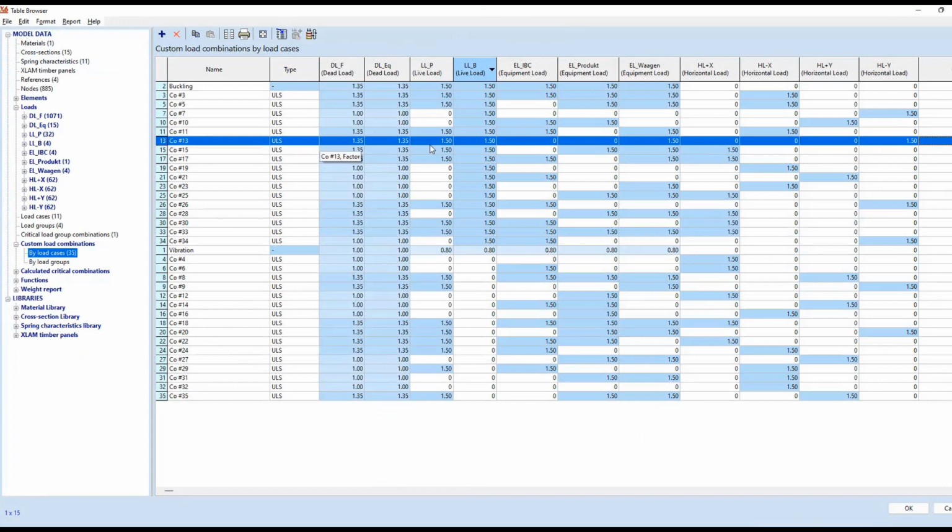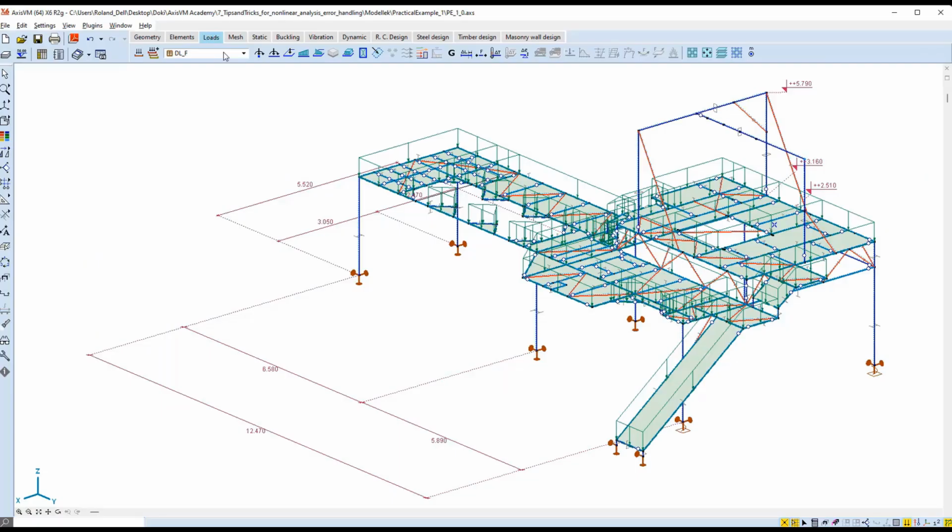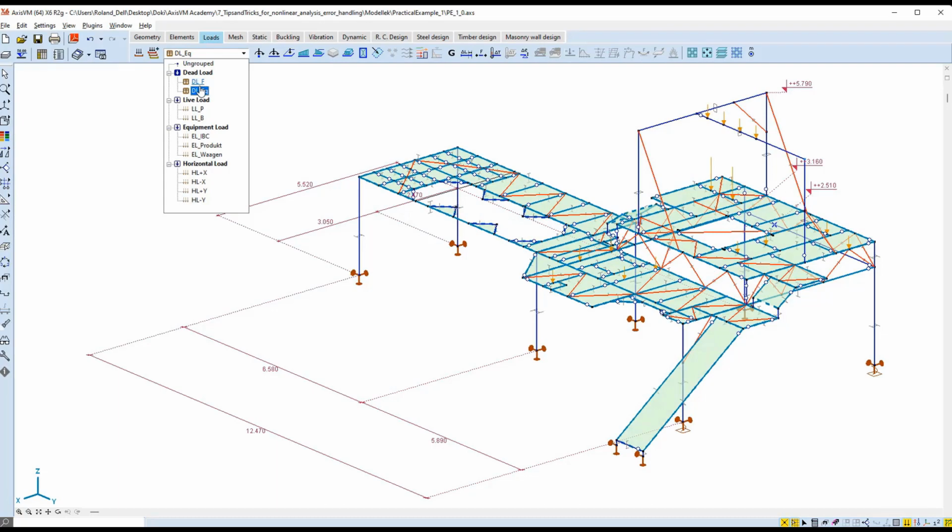There is a single ULS combination which is relevant for the presentation. It contains the following load cases: 2 permanent load cases for the dead loads of the structure and the equipment, 2 live load cases, one containing distributed surface load on the whole deck and one containing distributed surface load only on the ramp, and finally an equipment load containing nodal gravitational forces acting on the upper deck.